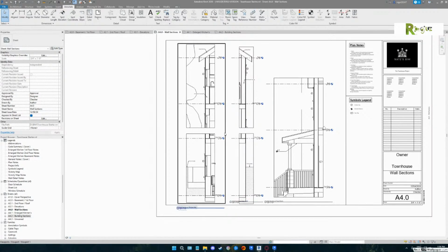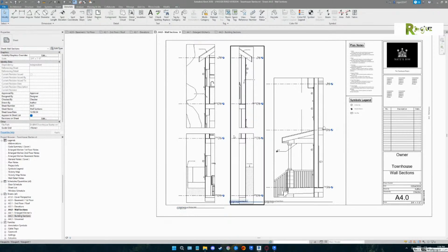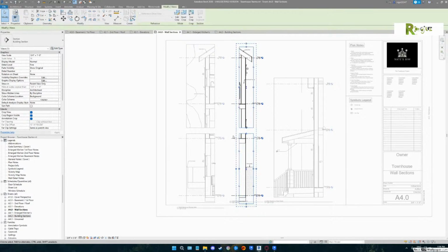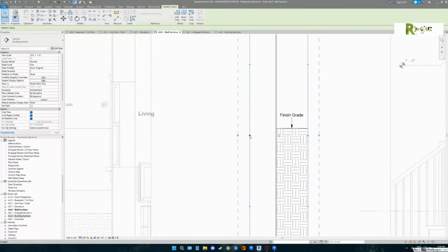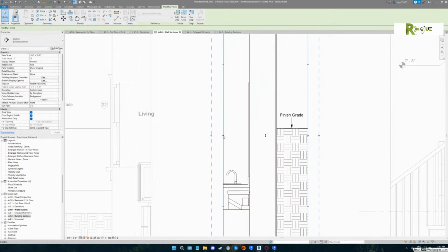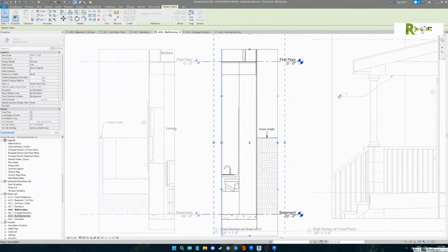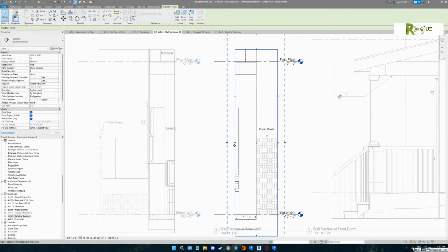So don't worry about that meaning something. But I will tell you that middle view, your section needs to be a little bit wider. You haven't included the whole wall on the basement floor because the basement floor wall is wide. Double click. Grab that crop boundary, and one of those inside faces, drag it in a little bit. No, not that side, that's the outside. This is the inside. That's it. So you've got to see the whole wall there, Nathan. See what it's sitting on. Right?